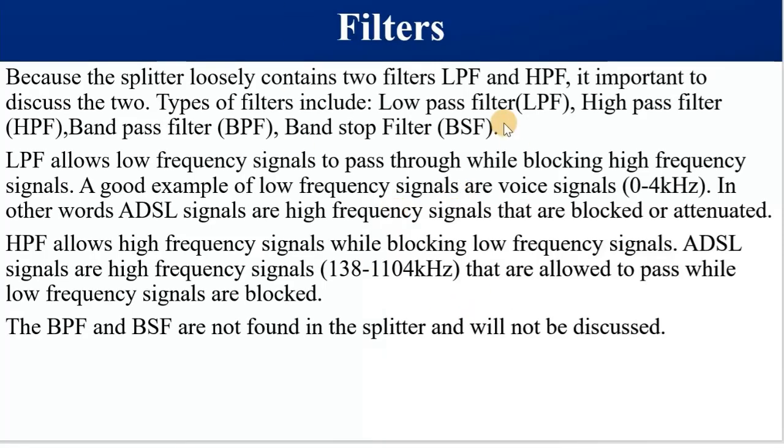Those with no background on what a filter is, we are going to cover that. We've got many types of filter. We've got low pass filter, which allows low frequency signals to pass through, for example, voice. We also have high pass filter, which blocks low frequencies, thus allowing high frequency signals such as ADSL signals to pass through. So LPF stands for low pass filter. HPF stands for high pass filter.